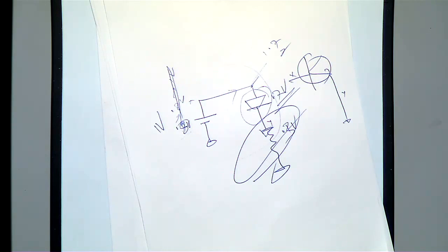The same principle we are applying to the transistor. That is the reason for this emitter degeneration. Even though you get some fluctuation here, VB is not affected much. That will appear across this RE. So that's what we do here, and this one is good.